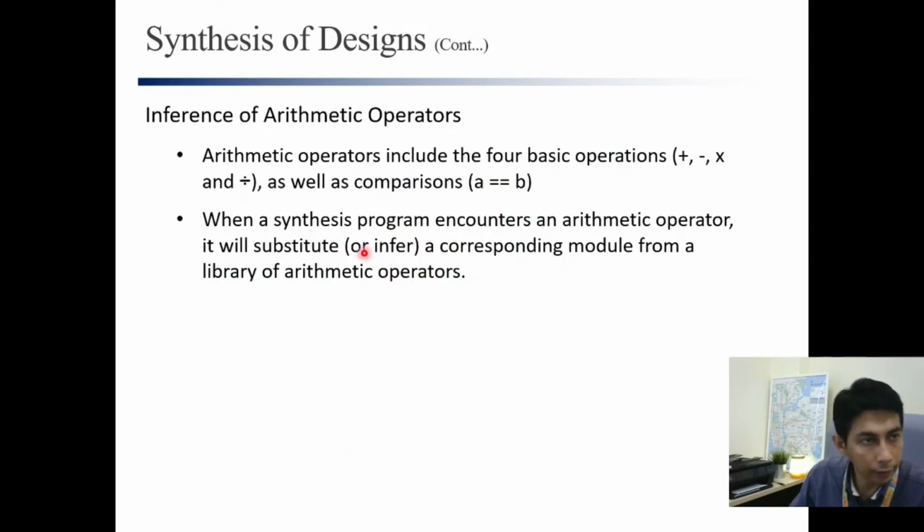Before that, inference of arithmetic operators. You can infer the arithmetic circuits, for example the adder, the subtractor, the multiplier, and the divider, by using these characters. For adder, you write plus.